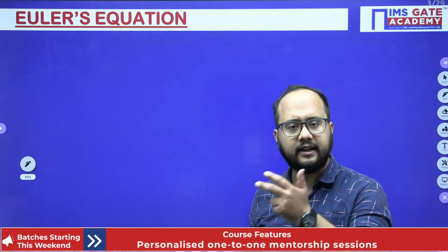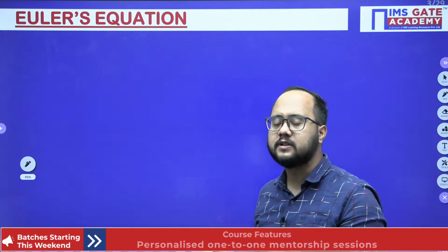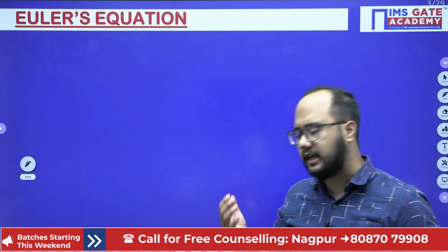Now the force part. In the last class, I discussed three equations: Reynolds equation, Navier-Stokes equation, and the Euler's equation. So if I ask you, what are the forces that we are going to consider in this Euler's equation, and which forces we are going to neglect? Those forces you should also know. Pressure and gravity forces are what we'll discuss in Euler's equation. The remaining forces like turbulent forces, compressibility forces, and surface tension forces, we are going to neglect.